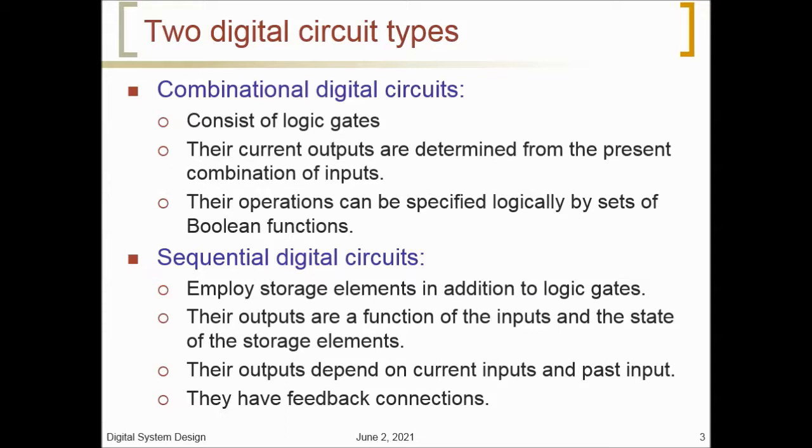Because the state of the storage elements is a function of previous inputs, the outputs of a sequential circuit depend not only on present values of inputs but also on past inputs, and the circuit behavior must be specified by a time sequence of inputs and internal states. Sequential circuits are the building blocks of digital systems.